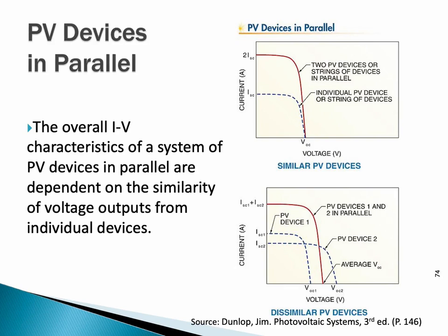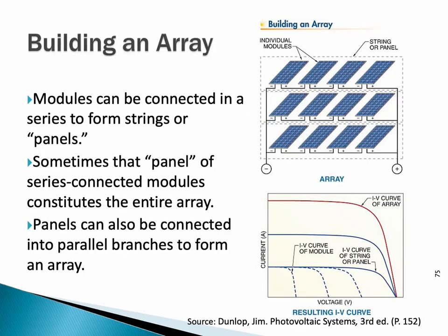All right. This is just power curves, IV curves, for when we start paralleling devices together. So voltage stays the same, but current is going to be additive, so the current line is going to be taller. And then if it was in series, current would stay the same, but the VOC line would stretch out more horizontally.